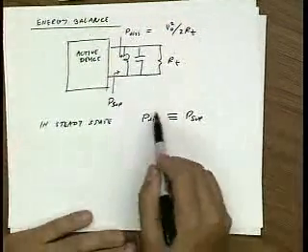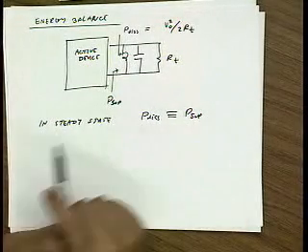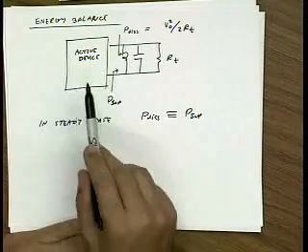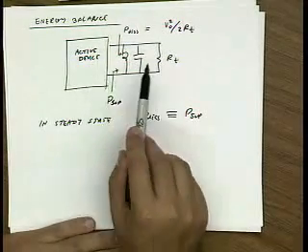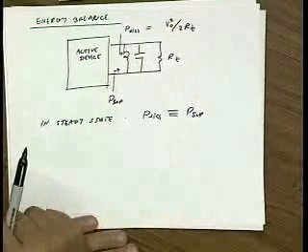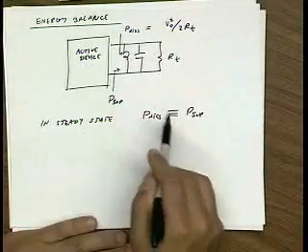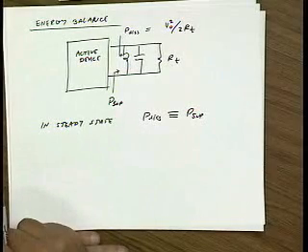This is the average power dissipated, this is the average power supplied. Now the power that the active device actually supplies can be bursty. It can supply bursts of energy into the tank, but on average that energy has to average out to the power that's being dissipated in the tank.